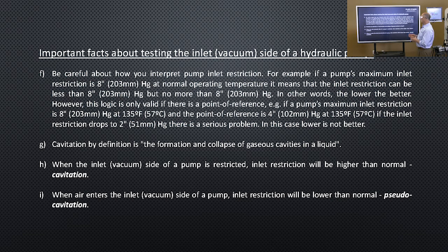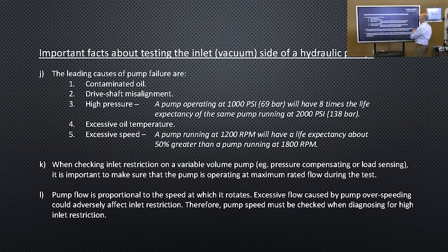When the inlet or vacuum side of a pump is restricted, inlet restriction will be higher than normal, which is again cavitation. And when air enters the inlet side of a pump, inlet restriction will be lower than normal, which is typically referred to as pseudocavitation.